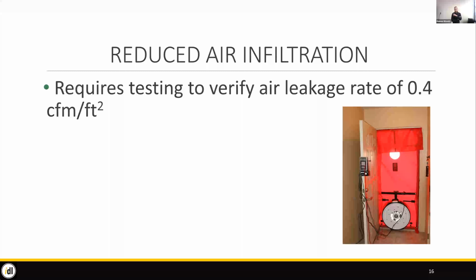And I think this does a service to engineers as well, because you'll get a much better sense of the actual infiltration for the building and whether you need supplemental heat or cooling, because that infiltration is about 35% of the total heating load in the winter in our climate, which is a lot.